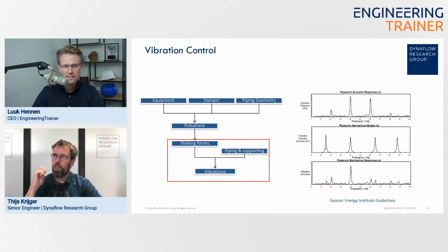There's usually for occasional stresses, for example, these shock loads for water hammer, they have to be combined with your other sustained stresses. For fatigue, that doesn't have to happen, because the fatigue allowable you can assess separately from your static stresses.